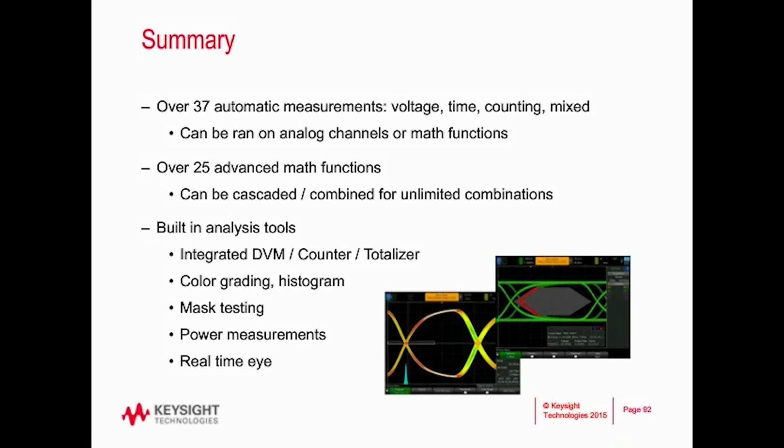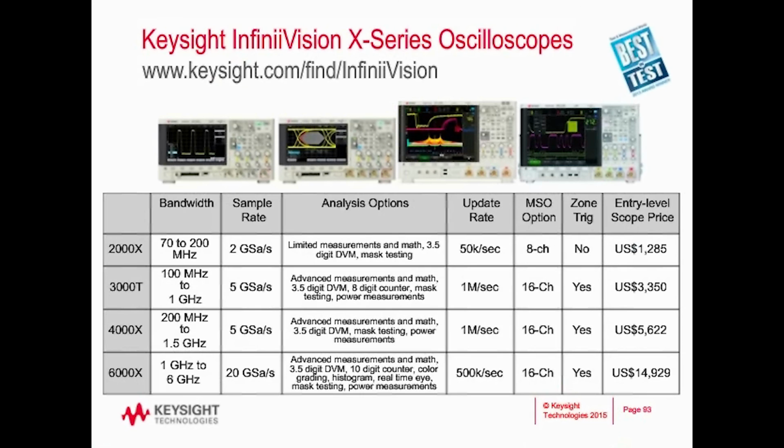And then we looked at some of our built-in analysis tools, such as the integrated voltmeter, counter, and totalizer, color grading and histogram, the real-time eye and jitter measurements, the power measurements, mask testing, and others.